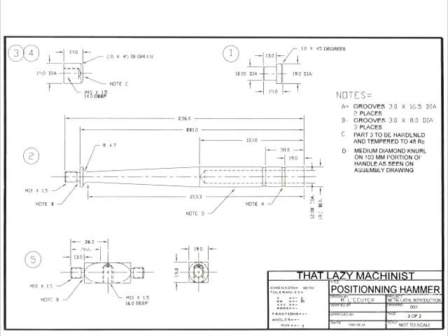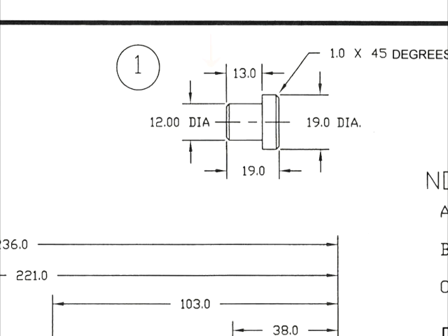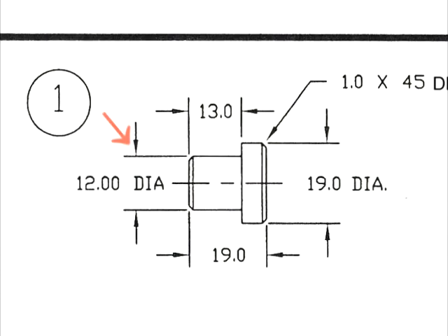Extension lines on their own are kind of useless, but if we have dimensions and we have extension lines, well, we need to tie both together. And to do that, we use dimension lines. Dimension lines are discrete lines that shouldn't stand out from the rest of the drawing. They are often separated into two parts, and that's to make room for the dimension itself. And they end with an arrowhead.